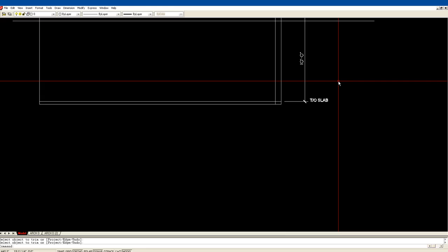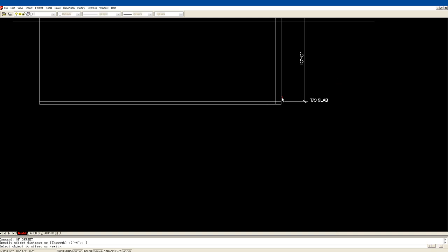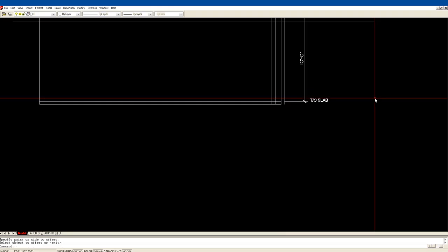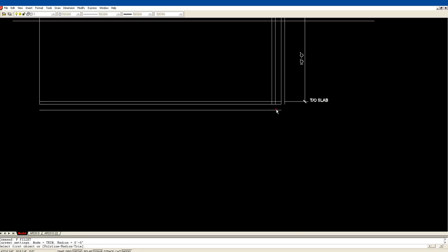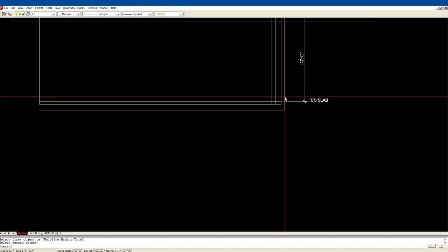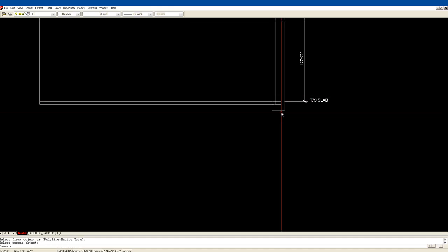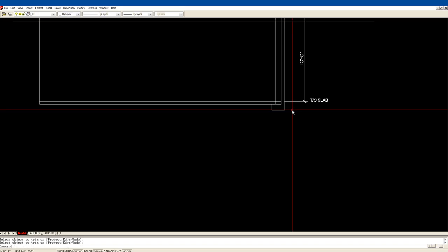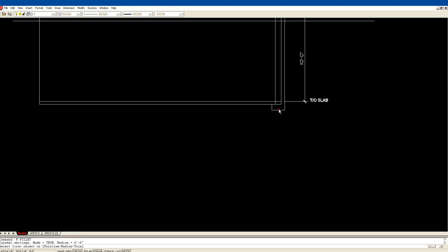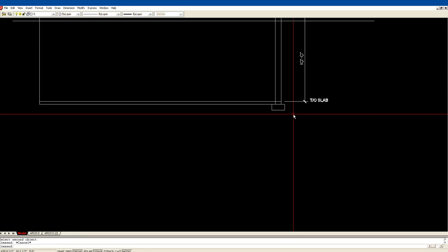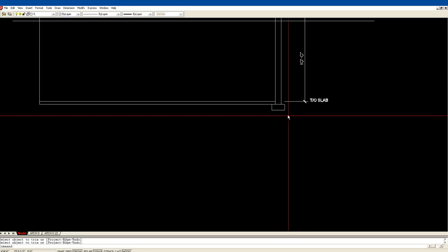And so if it's 18 inches minus 8, leaves you 10, divided in half is 5, so offset 5 inches from there to there and there to there, and we just said it was 8 inches thick, and so offset 8 inches, and just join these guys up. I'm just going to fillet that to that, and that to that, and I'm going to trim that to that, and I second fillet. Okay, and I'm going to trim that to that. Okay, so that's how this all works.